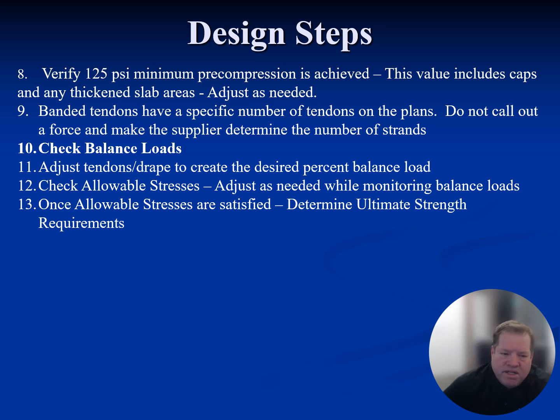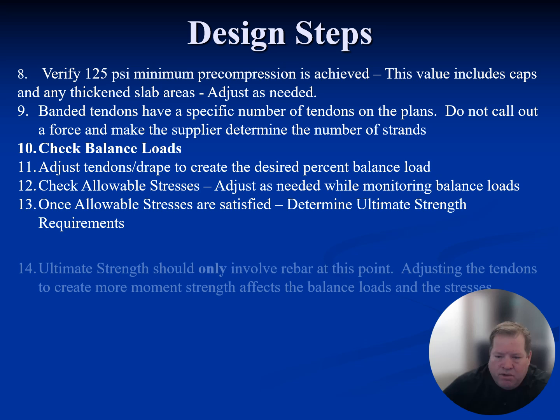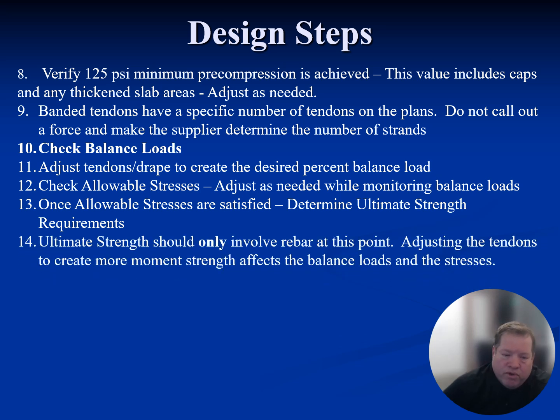For typical designs, in my opinion, the code minimum top rebar over the columns will govern the vast majority of the systems. If you're designing a slab where 90% of the columns need more rebar than the code minimum, I'm going to guess that your slab's too thin. So that's another thing to keep you out of trouble, hopefully.